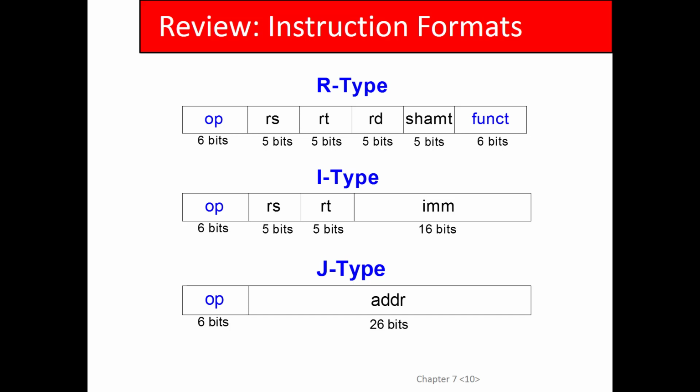So there's an address inside the register. The register file holds addresses too. I should have mentioned that. In addition to intermediate results for computation, it also holds addresses. So you'll have an address in the register file, and then you'll take that address out and add the immediate to it, if you're doing a load or store. And that gives you an effective address. That's how you get to 32 bits.